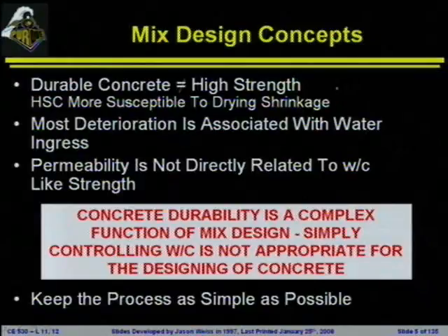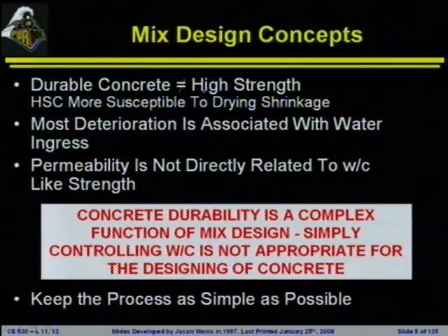Few other things that I'll jump into before we get into mixture design. Durable concrete is not the same as high-strength concrete. You can make fantastic high-strength concrete that cracks like crazy or isn't durable. All right, high strength and high performance are not synonymous. Durable concrete is not synonymous with strength. Many times an increase in strength comes about because of reduction in water to cement ratio. A reduction in water to cement ratio has benefits in terms of durability, but they are not synonymous with one another. The place where this becomes the most important is it is obviously not an appropriate way to specify durability to specify strength.